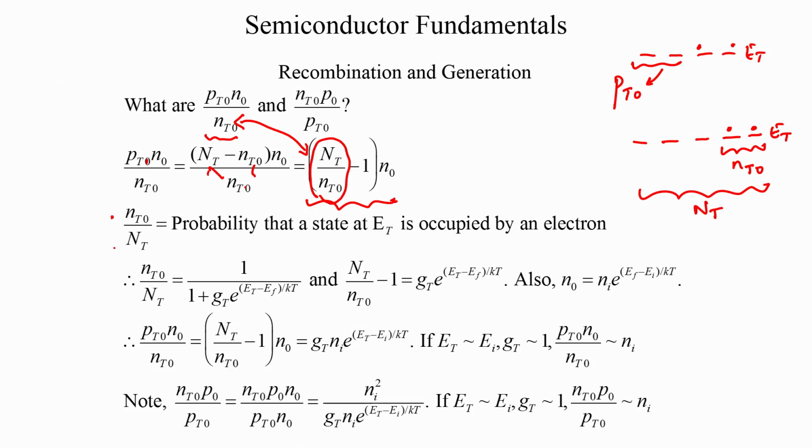which basically implies that we are talking about the Fermi function, right. So, the Fermi function gives you the probability that the energy states at energy level E are occupied by electrons. So, f of E, which we discussed earlier, is that probability. So, we are talking about the same case, and we had looked at this condition even in the case of doping, when we looked at the number of donor sites or the dopants that are ionized as compared to the total dopant concentration. So, it is exactly the same argument.